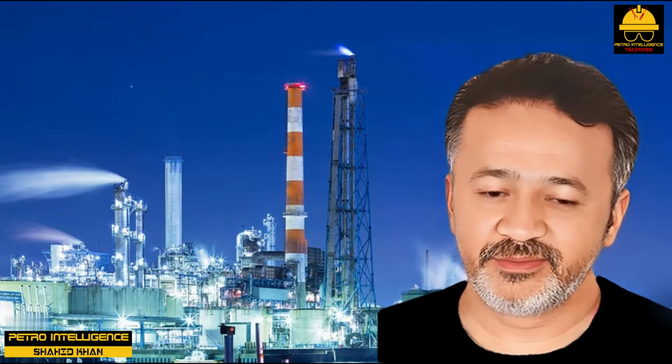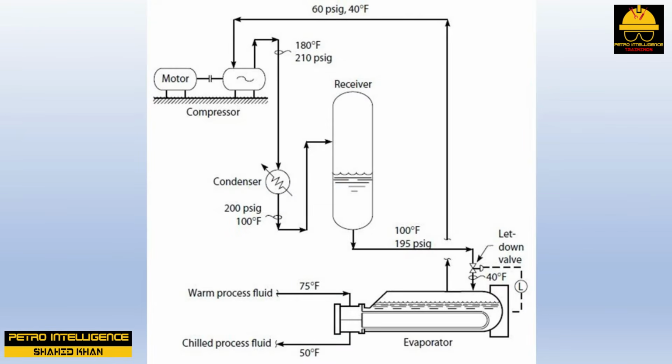Suction throttling. Suction throttling is the preferred method as shown in the picture. Suction throttling also wastes energy. Whenever a control valve is partially closed in any service, energy is always wasted. But with a fixed-speed centrifugal compressor, it is still the best option. As the suction valve is closed, two things happen. The flow of refrigerant vapor to the compressor is reduced, and the compressor suction pressure drops.